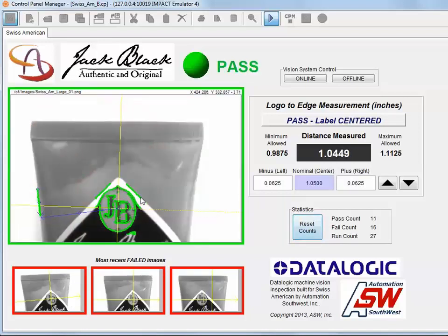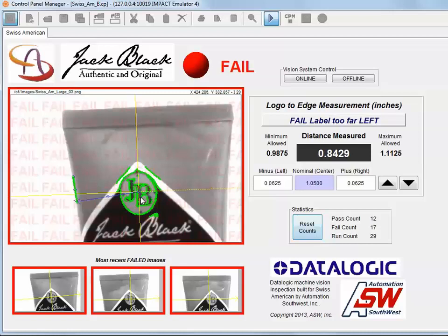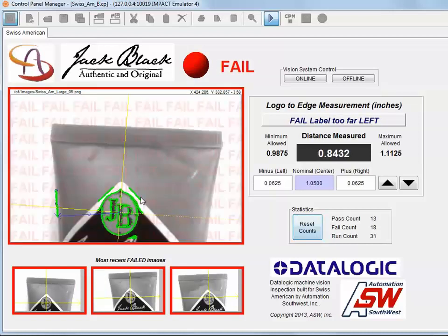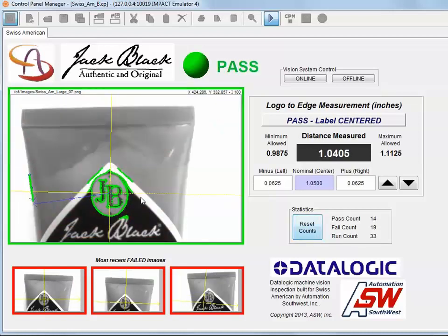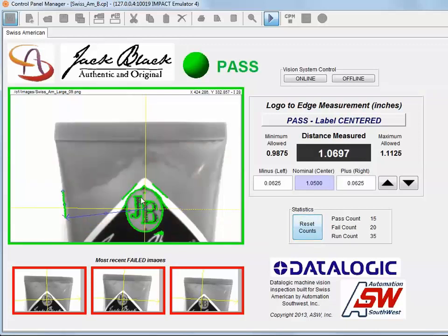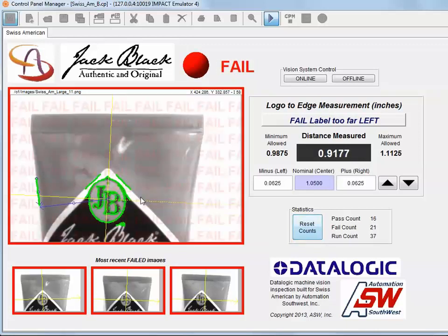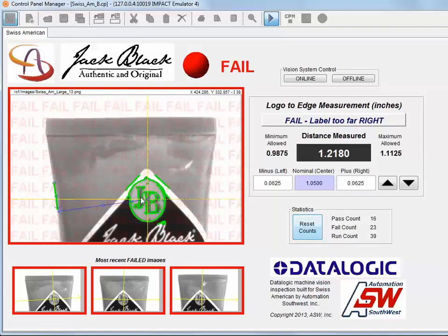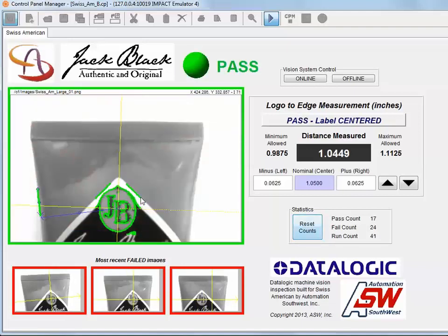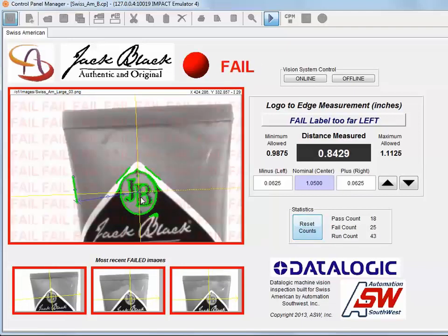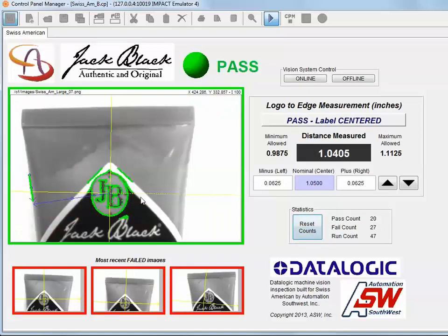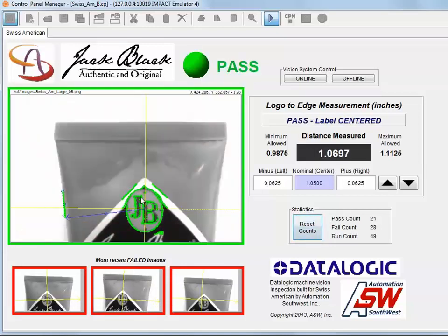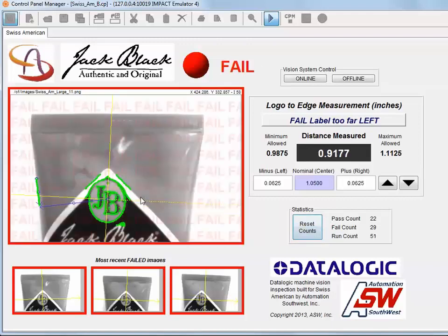So in summary, this is a very straightforward and successful machine vision application. I would say in terms of repeatability, it's again a Datalogic A20 series camera. We had an 8mm lens approximately 4 or 5 inches away, and ambient lighting. Just an absolutely quick and easy application.